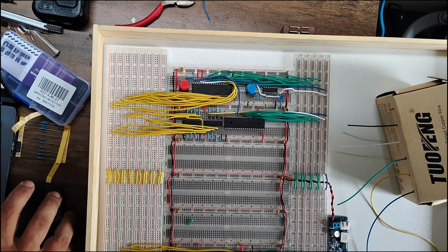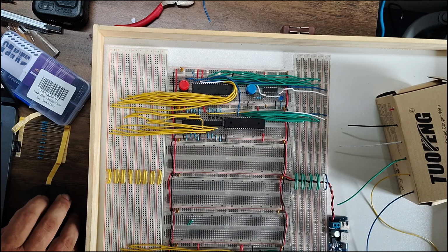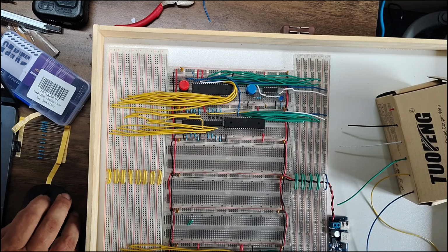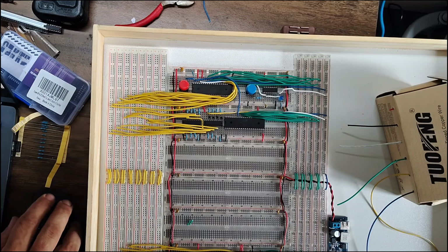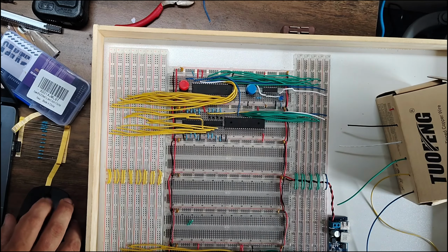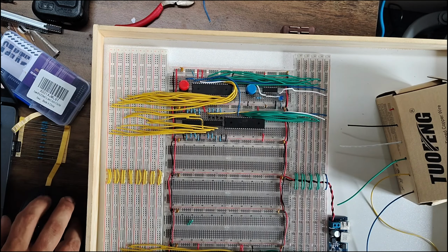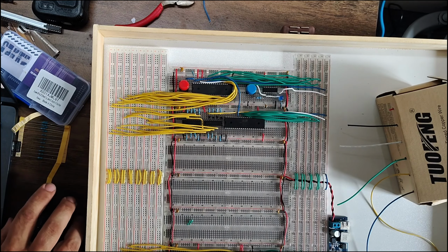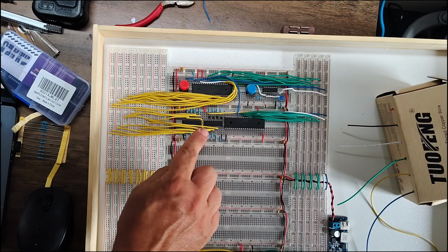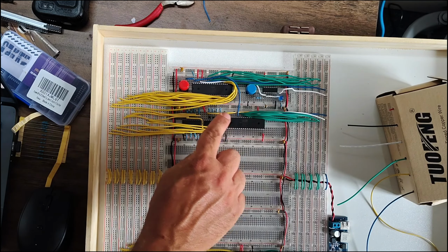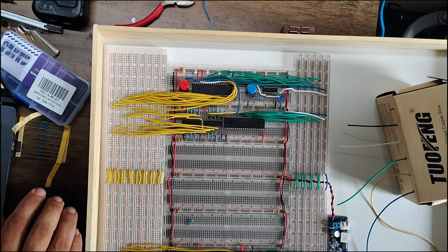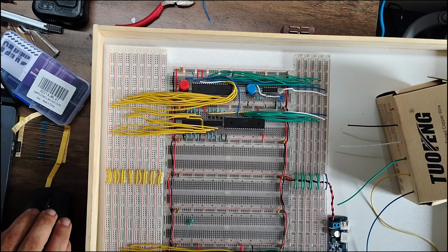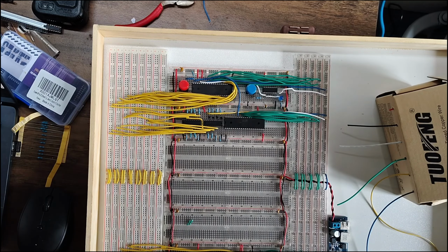And to that end, we are going to have to connect the last 4 of these address lines to the next 4 pins. It is just worth saying that the pins run backwards basically, so the shortest wire has to go to the first one, and then the longest wire goes from furthest left to furthest right. So I'll get all those connected up, and then I'll come back to you.